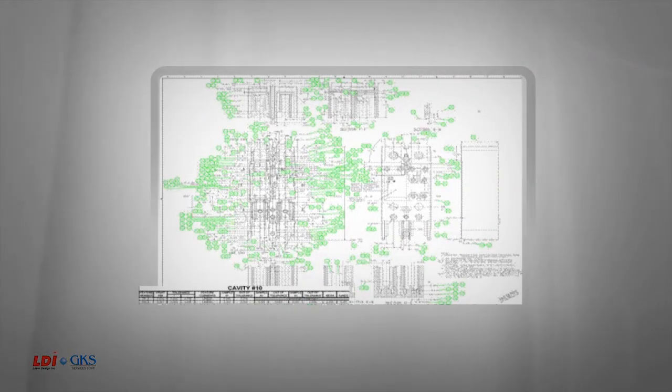This is a markup for using traditional metrology to find a deviation on a part. There were 711 dimensions on 3 sheets. There were 2 dimensions that were out of tolerance. To show you how inefficient and expensive traditional metrology can be, this took 264 hours for 3 cavities for a total cost of $79,000 to inspect this, and more importantly, it took 32 days.